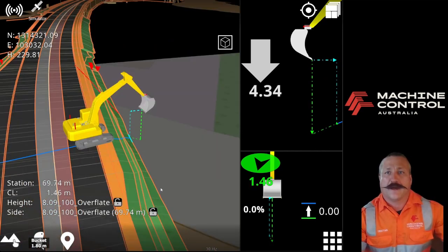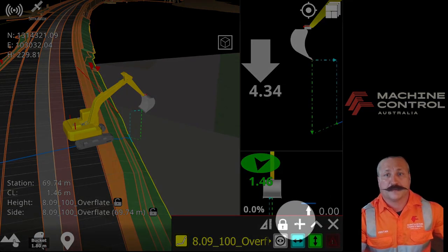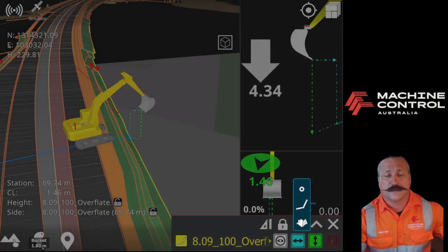If you need a different angle, you can do this by creating an infield design off the edge of the polyline, whether it's straight or curved. Selecting the edge of the polyline and creating a profile for any angle of fall is not just possible, it's simple. So if we come down here to our line of the edge of our project, we come down to the bottom here, we can then hit the plus, we then select surface, which is the bottom one,